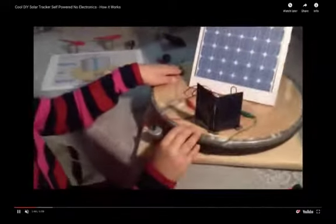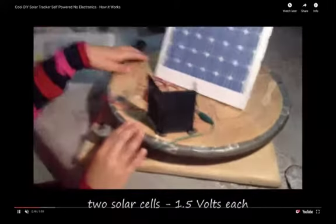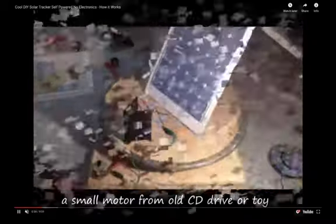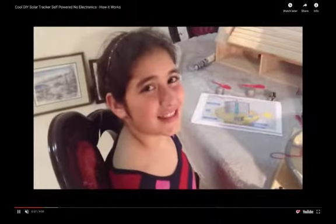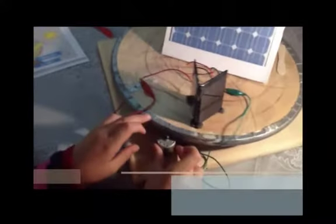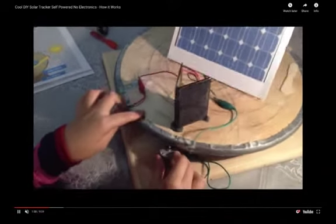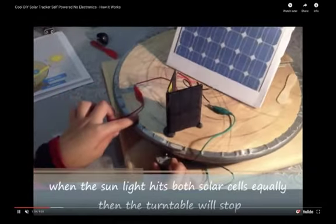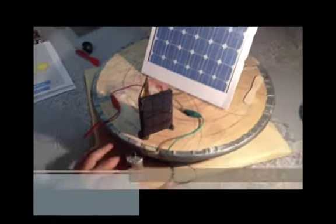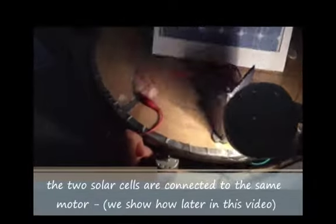So you can see there's a solar panel, okay? And the idea is she's using the solar panel to drive a motor, which will always point towards the sun, essentially. And you can see the basic idea is that if it's pointing slightly away from the sun, there is a mismatch in the output from these two solar panels, and that will drive the direction of the motor that turns the turntable. In other words, you can see in this example, she's pointing the light on one side, it'll turn.